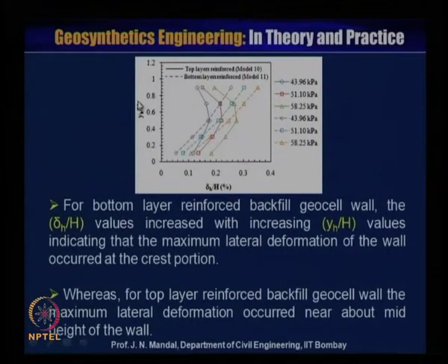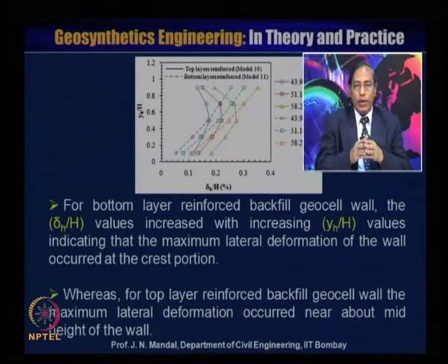Now, here also the Y_H by H to delta H by H in percentage relationship for the top layer of the reinforcement, model 10, and bottom layer of reinforcement, model 11, under this load. From the bottom layer of the reinforced backfill geocell wall, the delta H by H value increases with increasing Y_H by H value, indicating that the maximum lateral deformation of the wall occurs at the crest portion.